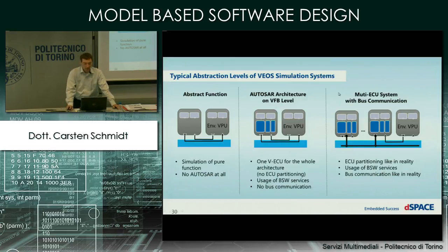And so you would basically model the virtual ECUs in the most realistic way, using a quite good approximation of the base software that will be used later, and then you will configure how the different signals that are produced by the software components are mapped to bus signals, and then this communication is really sent over a simulated bus and will go to another ECU.